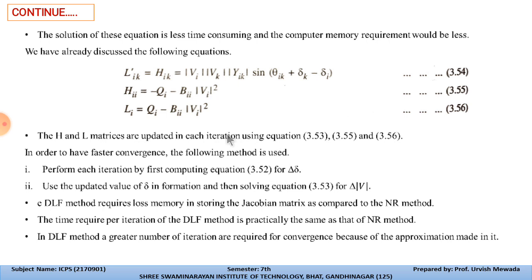Whenever we compute the load flow studies with the help of the DLF method, perform each iteration by first computing equation 3.52, shown in the previous slide, for delta delta, meaning the change in the load angle. Second, use the updated value of delta in the formation, and then solve equation 3.53 for delta mod V.